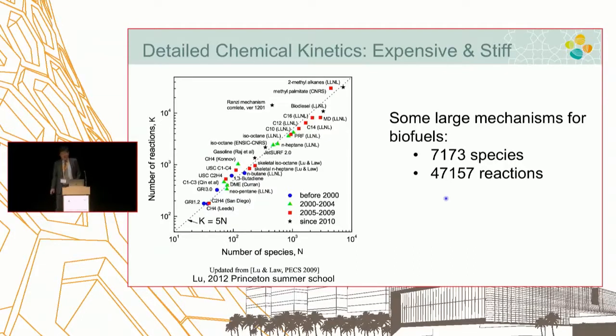Each of these reactions deals with different time scales. How is that time scale determined? Well, in a simple Chemkin format, the activation energy, the pre-exponential factor A, E, alpha, those are the rate constants. If you plug in, then you know the rate, and that is actually determining the chemical time scale. Just as there's a huge spectrum of time scales in turbulence, in chemistry it's even more. So you have to deal with that. This is a common terminology we call stiffness.